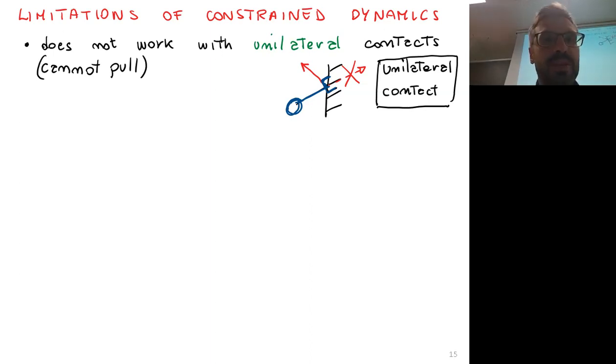We did that because we want to ease the integration of the acceleration, because we have both torques and contact forces, and we wanted to get rid of the contact forces to do a simple integration of the acceleration, but in a lower dimensional space where these contact forces are not present. But this doesn't mean that these contact forces do not exist at all.